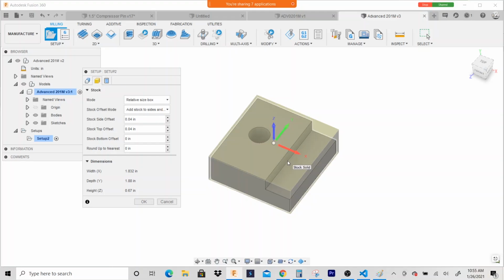What you would have to do is, you can't edge find the middle of the part, so you would have to touch off the side of the part, measure the part, divide by 2, and then offset that distance. You know what I mean? That's why on square or rectangular parts, I always put the origin in the corner. I think Garrett puts it in the middle, because when you first start learning Cartesian coordinates, it's helpful to put it in the middle. But when you actually start making parts, you really want to put it in the corner.